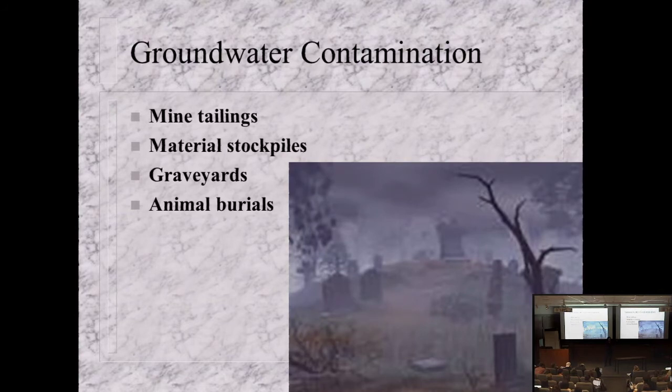That means you're in a groundwater recharge area. So whenever it rains, the water's picking up the chemical signature of the arsenic, plus any bacteria, viruses that the deceased were made ill by, any sort of organics, and dumping it out into the rivers and the low points. So wherever you have an older graveyard on the landscape, I guarantee you have an arsenic problem in the river down gradient of the graveyard.